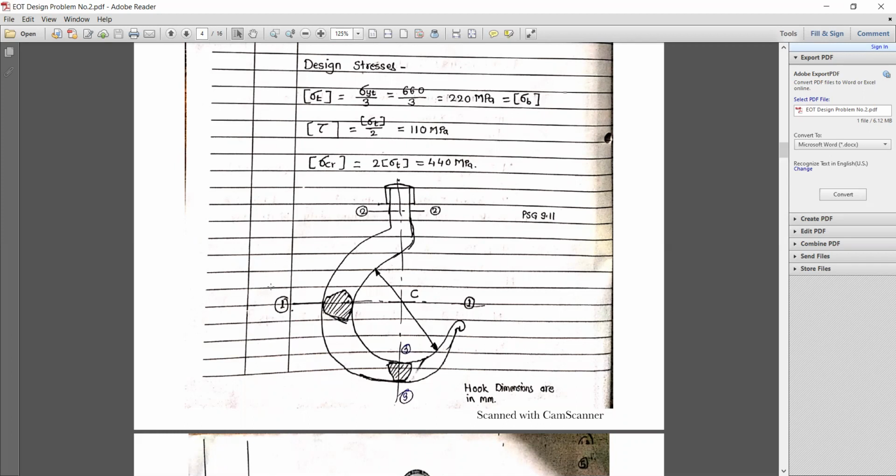In a previous design we also discussed the cross section, with the inner fiber and the outer fiber. We select a trapezoidal cross section, with more thickness at the inner fiber and lower thickness at the outer fiber.